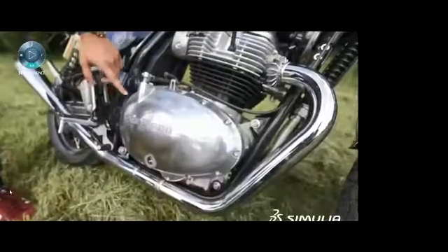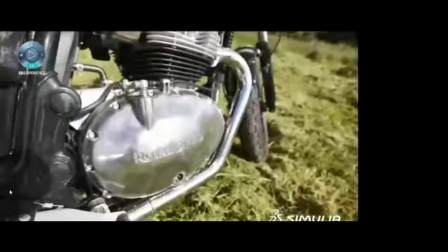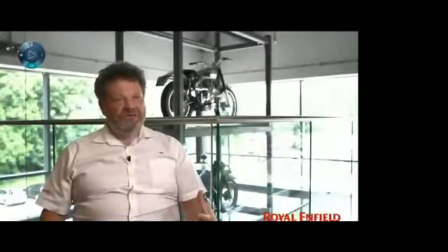There are ribs inside the covers. We developed a methodology which is basically called a sizing optimization. That basically shows us how the ribs should be aligned based on a frequency based sizing optimization. Key to a good engine durability, I have found from previous experience, is to make sure that the crankshaft has a very good durability. Earlier, we used to assess the durability individually, like we assess the durability of the con rod, or we assess the durability of the crankshaft separately. But now we have a multi-body dynamics model, including the flexible bodies with piston, con rod, and the crankshaft.